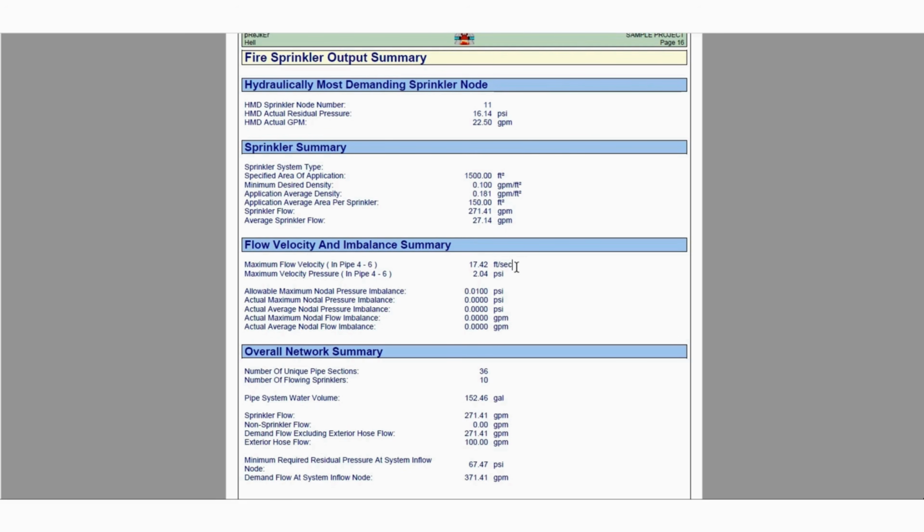But if the velocity we get from the calculation is more than 20 also, no need to worry, since NFPA 13 does not prescribe any limitation for above ground piping. However, for underground piping you need to check NFPA 24 for velocity limitations. As per my knowledge, there is no limitation requirement for underground piping.